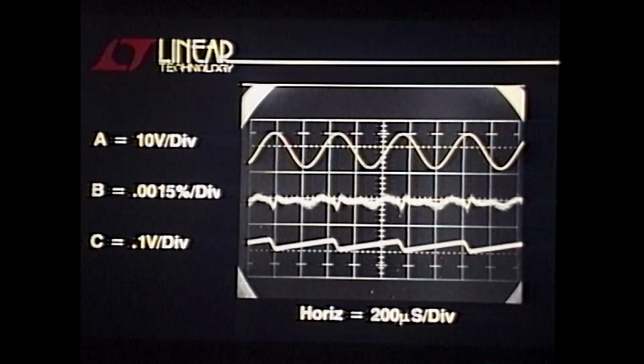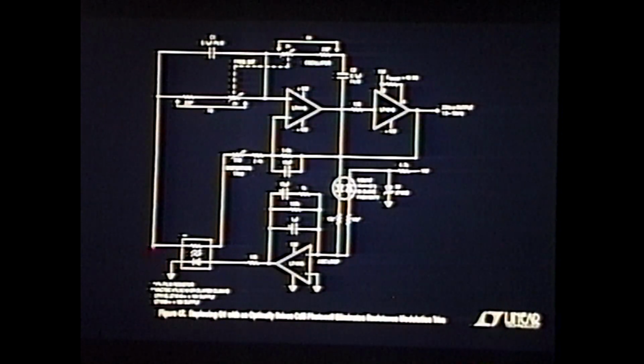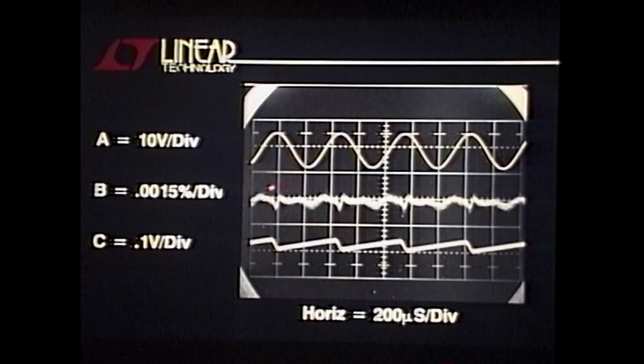Those LED-driven photocells have other problems. For instance, they have horribly asymmetric slew, which is to say, if you drive the LED on, the photocell responds much faster than going off. So you have this AC asymmetry in your loop, which you're going to have to account for in your gain control time constant. But in terms of the stated objective of getting rid of the channel modulation problem, it did it. You get the same performance.